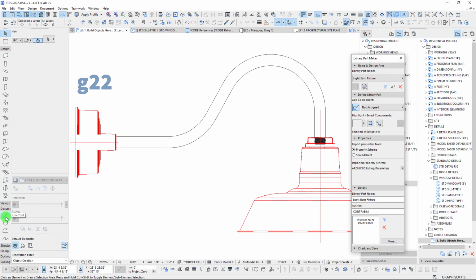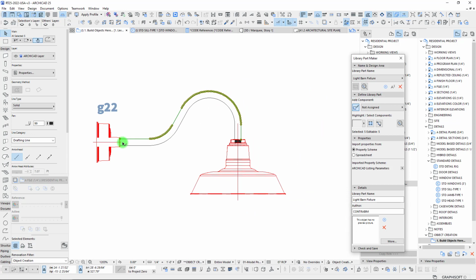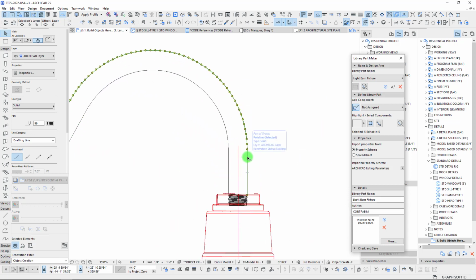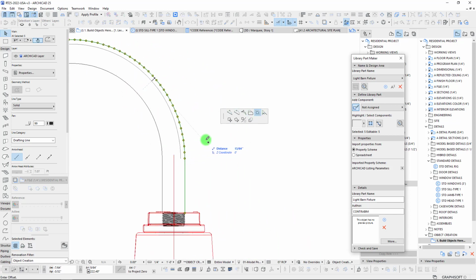This next step here, I'm actually going to start this. Really, we need to connect these, and what we're actually going to do here is extrude a circular shape to complete this gooseneck for us. But what I want to do to begin with is offset all of these if I can, and create a bit of a copy here so that we can get a center line essentially.